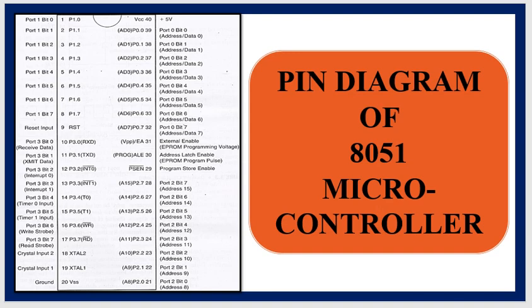Pin number 16 is WR, write to external RAM, and pin number 17 is RD, which reads from external RAM. Pin number 18 and 19 are called XTAL1 and XTAL2, which are the internal oscillator input and output.